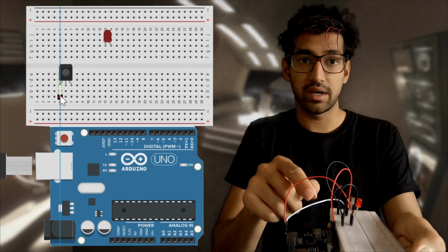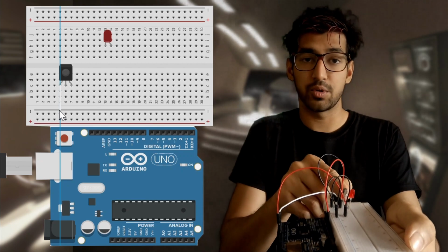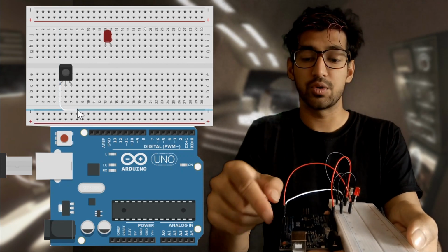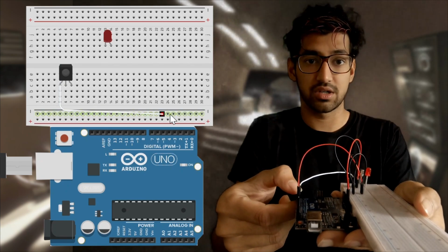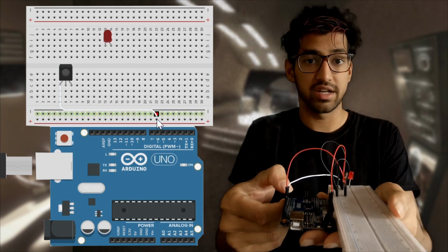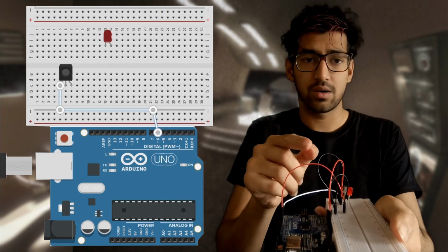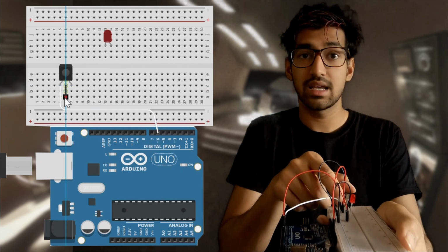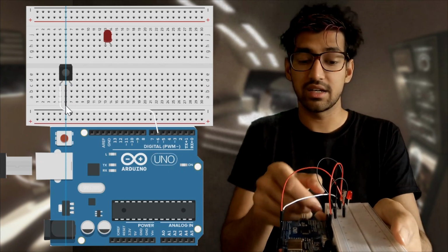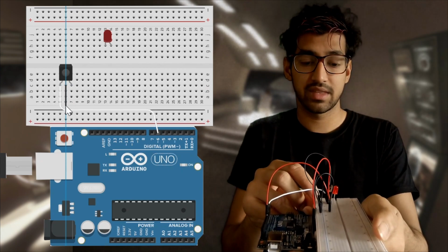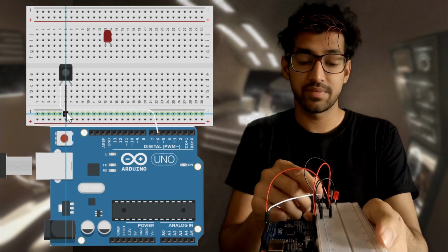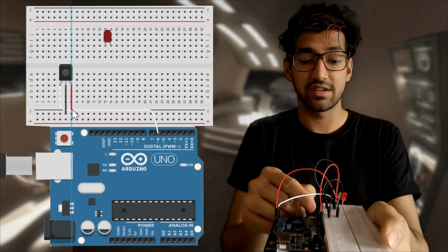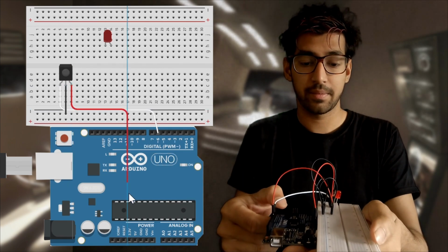Connect a white wire which is connected to the sensor port of the infrared to 5P and the other port to the 6 on the microcontroller, which is a pulse width modulation port. Connect a black wire from the middle port on the infrared sensor at 6B and connect the other end to the negative on the breadboard. Connect a red wire at 7B and insert the other end at 5 volt in the microcontroller.